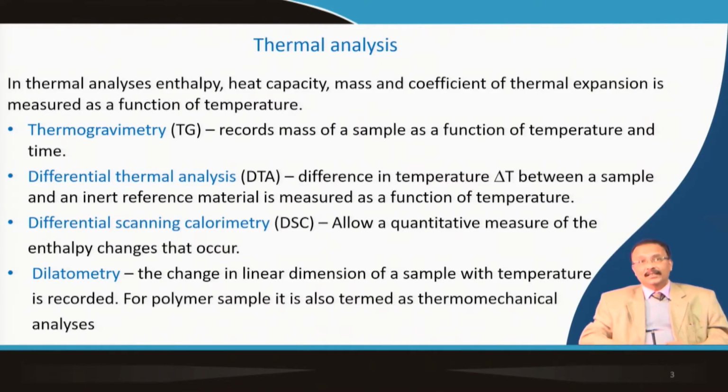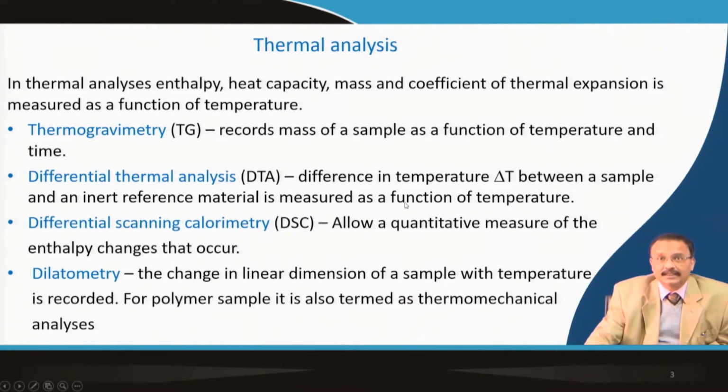So, basically in thermal analysis, enthalpy, heat capacity, mass and coefficient of thermal expansion are measured as a function of temperature and in some instances as a function of time. In thermogravimetry, we record the mass of a sample as a function of temperature and time. In differential thermal analysis, the difference in temperature between a sample and an inert reference material is measured as a function of temperature.